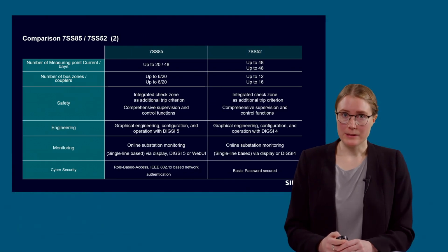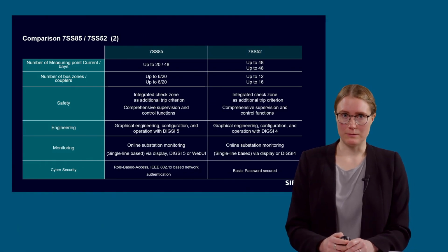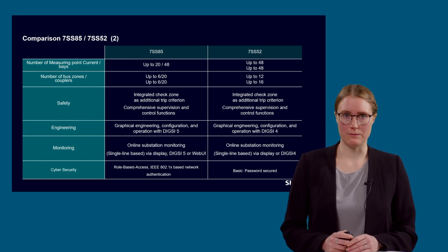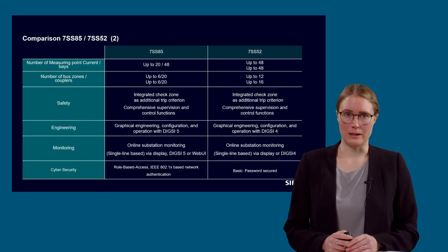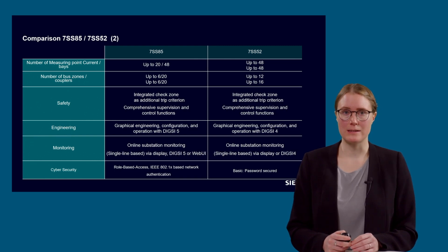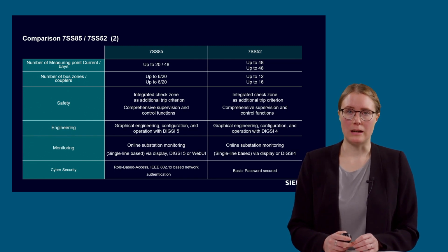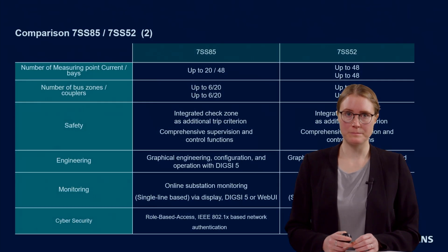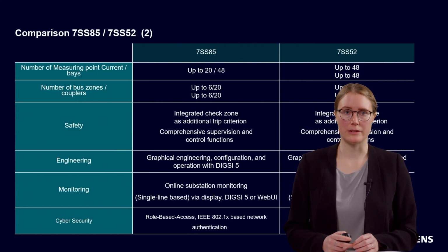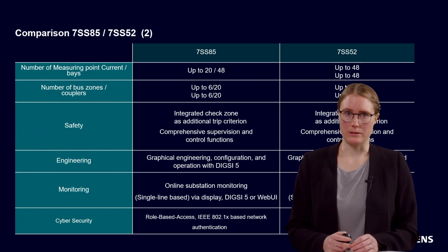The topic cybersecurity is definitely a selling point for the 7SS85. Since the device is a part of the Sipotec 5 family, platform functionalities like role-based access control and IEEE 802.1X based network authentication can be integrated. With the 7SS52, we can only offer basic password security.